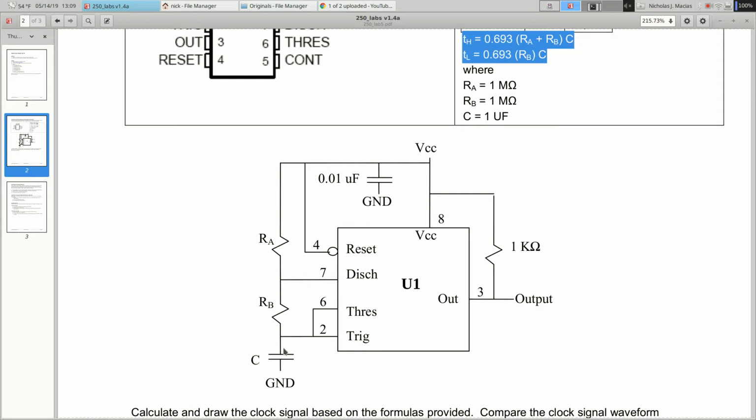Electrically, there's a lot of ways you can do this. But the fewer wires you use and the simpler the layout, the easier it's going to be to get it correct or to debug it if it's not quite right. And the better it's going to work. Pins 2 and 7 are connected through a resistor. Easiest way to do that, take your resistor, put one lead on pin 2, put the other lead on pin 7. So it's going to go across.